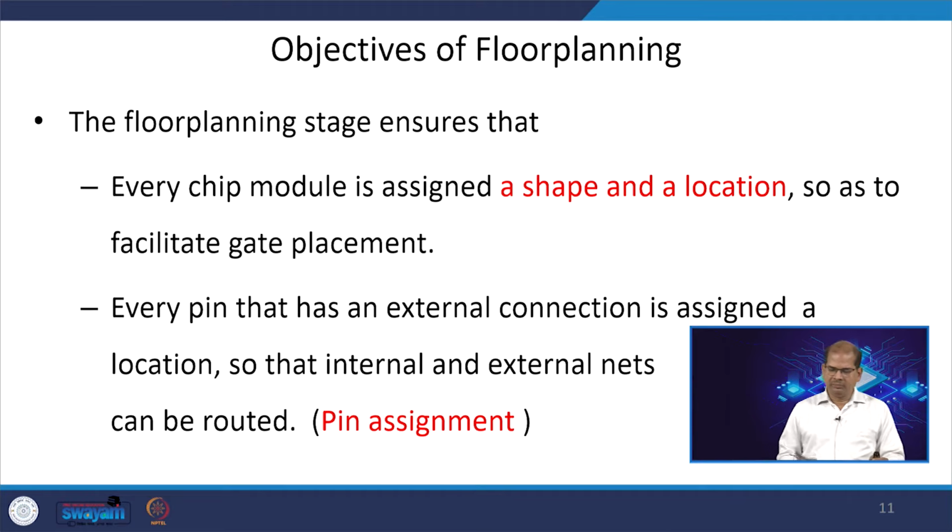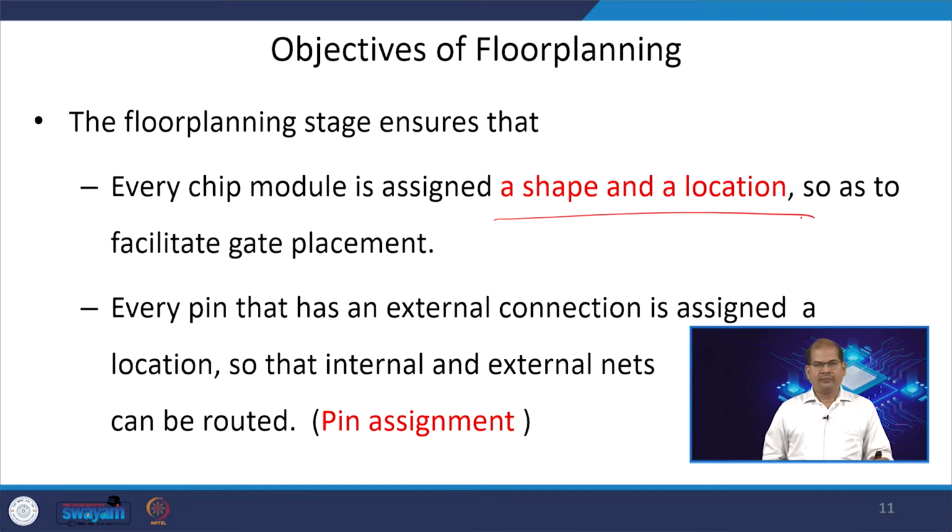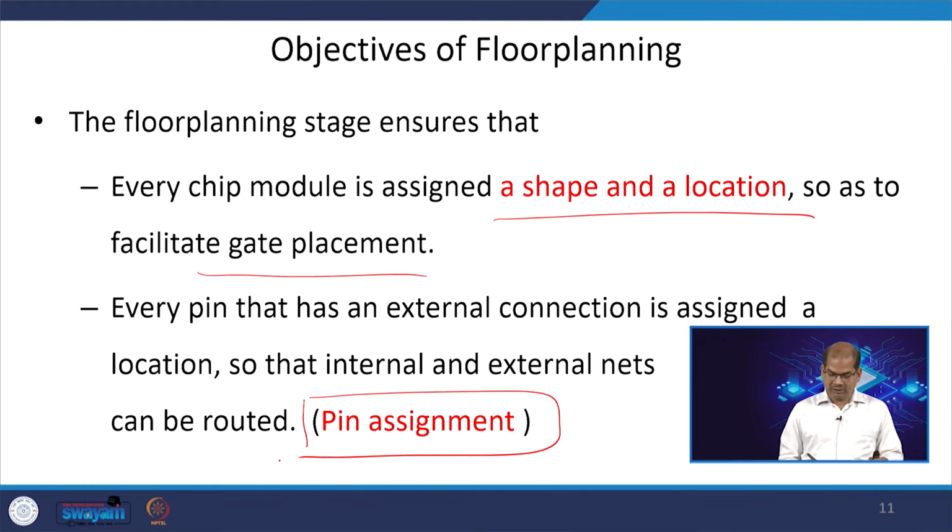So, what are the objectives of floor planning? There are several objectives. It basically determines the shape and location of each of the blocks, which is useful for gate placement, and it is also used for pin assignment. What is this pin assignment? It is actually for every pin that has an external connection.